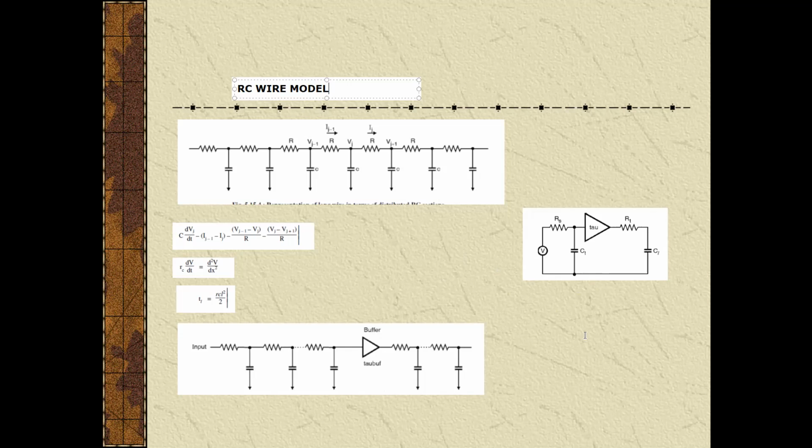The wire parasitic role in routing. In this case, the transitions from the routing layer can provide an extra resistance to the wire. This kind of resistance is popularly known as contact resistance. Therefore, the single layer wire routing technique is used to avoid unnecessary extra contacts, further reducing the contact resistance, and the contact hole diameter is increased, which leads to crowding effects.